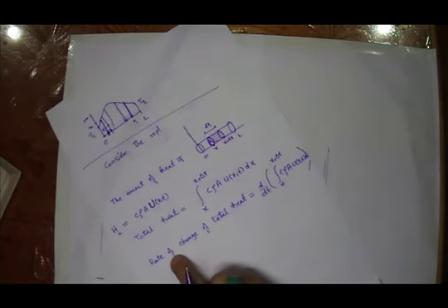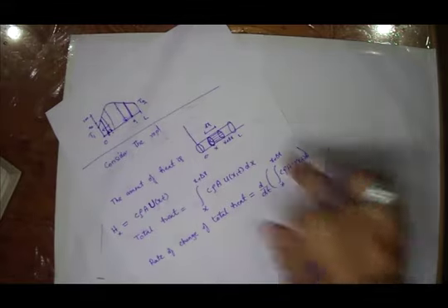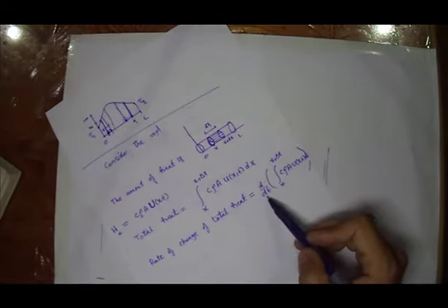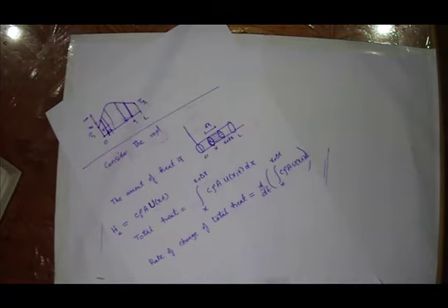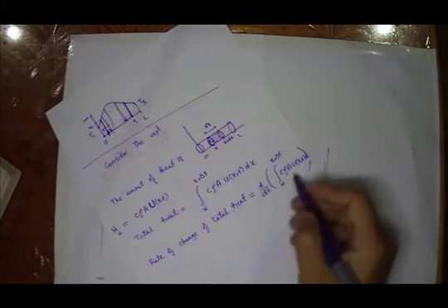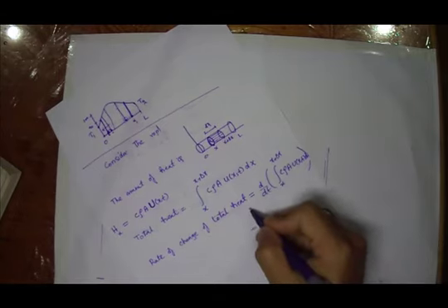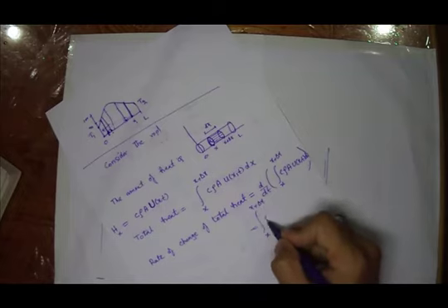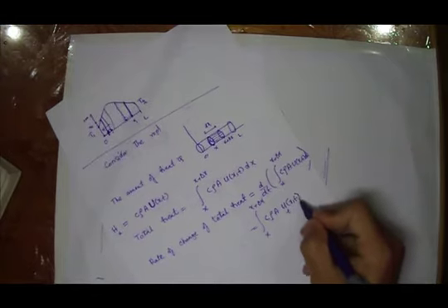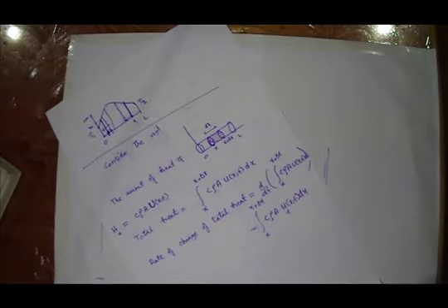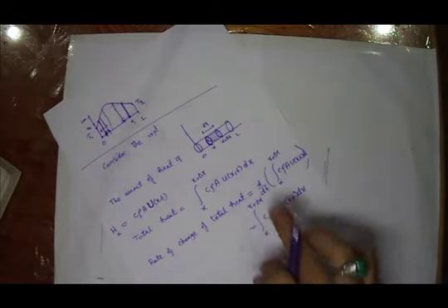So this is the rate of change of total heat in this cross section. Now from elementary calculus, we can write it as the integral from x to x plus del x of c rho a u_t(x,t) dx. This is the total rate of change of heat energy in this small portion.